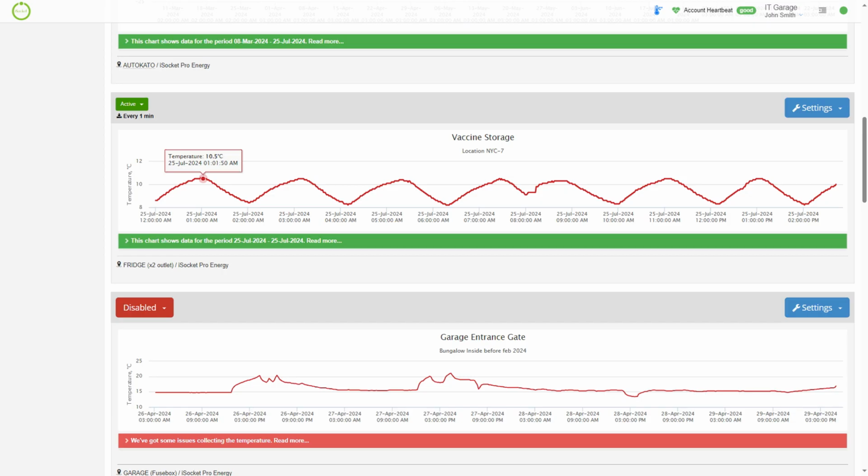So in your big fridge, you will have quite different temperatures. If you set it to 5, you probably don't even have a 5 somewhere. Maybe just in one location near the compressor, usually at the bottom of the fridge, if it's a standalone fridge. In other places, you can have 10. So if you are interested in a specific location in your fridge to monitor something like vaccines, you need to place the sensor close to it.